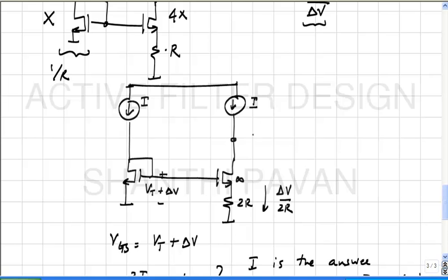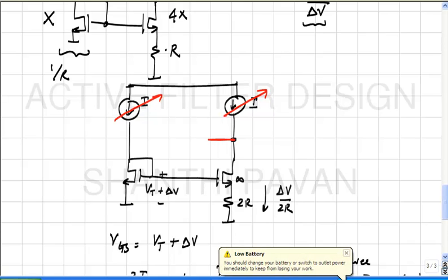If this voltage is going up, it means I is more, which means I must decrease I. On the other hand, if this voltage is going down, I should increase I. So both these, in other words, are tunable current sources, which are controlled by this potential. Does it make sense? What is the easiest tunable controlled current source that you know, which varies in relation to a voltage? Two PMOS transistors, both these currents must be identical, correct.